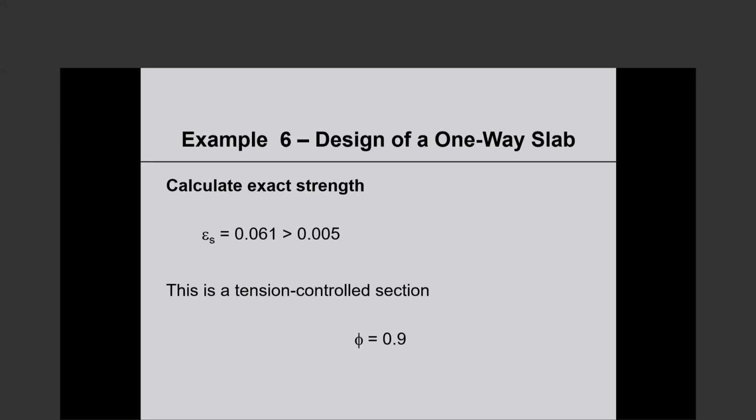Anyway, I'll try to figure it out for myself. But if that's what happened, because the concrete strength didn't reach the target strength, and that made the beam over reinforced, there is nothing that you can do or are supposed to do. You will just have to live with the situation. This will be borderline over reinforced.